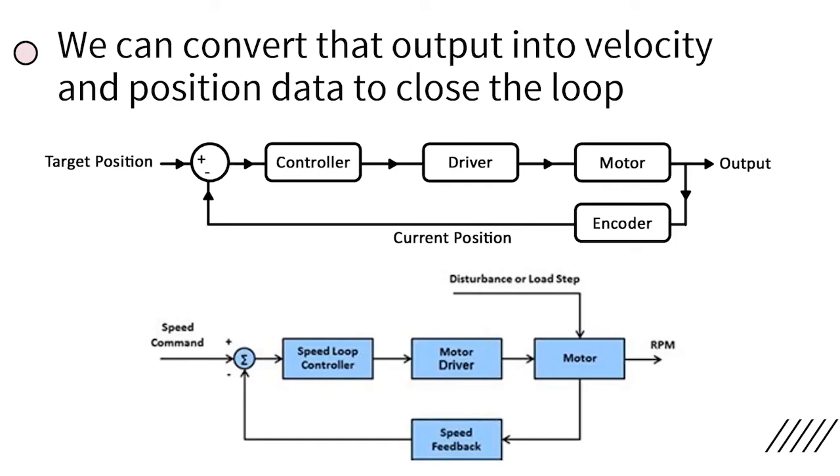Knowing the diameters of the wheels, we are then able to take the total rotation that we've counted and convert that into a position of our system. Similarly, if we're measuring the time as well within the internal clock of the controller, we can then convert that rotation into angular speeds. So then we can directly compare the speeds of the different motors to see which one's matching up. For instance, if one of the motors is moving a little bit slower than the other, I can increase the duty cycle to assign more voltage to help compensate for that.